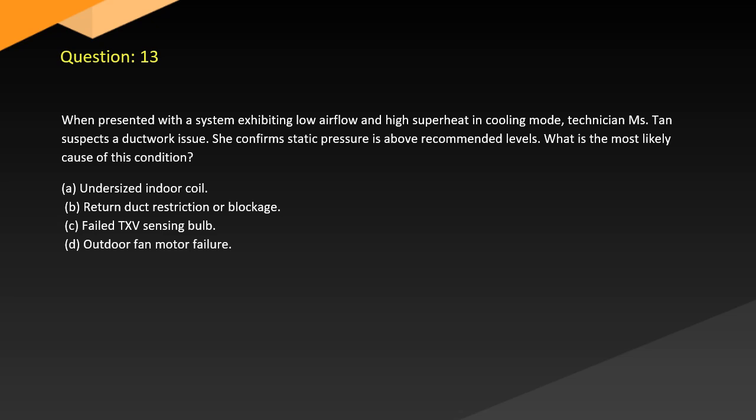Question 13. When presented with a system exhibiting low airflow and high superheat in cooling mode, a technician, Tan, suspects a ductwork issue. She confirms static pressure is above recommended levels. What is the most likely cause of this condition? A. Undersized indoor coil. B. Return duct restriction or blockage. C. Failed TXV sensing bulb. D. Outdoor fan motor failure.